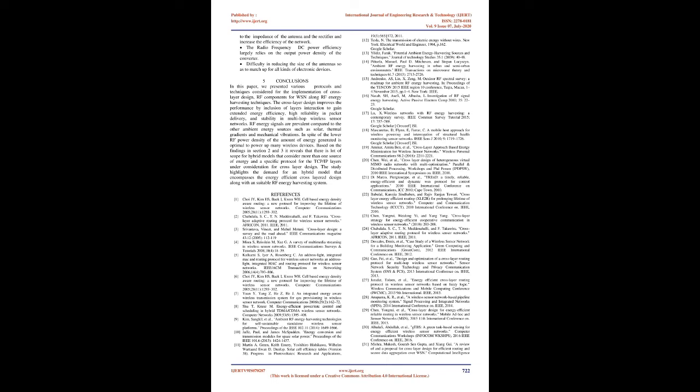Lee et al., 2019, proposed a rectifier circuit that utilizes the MOSFET threshold voltage for RF energy harvesting. The rectifier is designed with SMIC 0.18 µm CMOS technology with an improved efficiency of 72.3%. Wu et al., 2016, proposed a simple converter that uses 940 MHz signals for a reduced power wireless power transfer, WPT, system. By testing various diodes and topologies, a rectifier circuit is designed as a very low ambient energy collecting system.